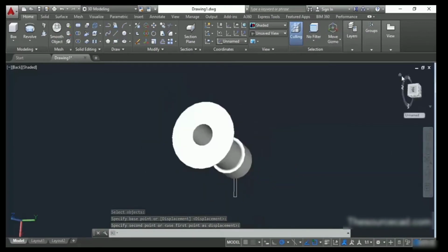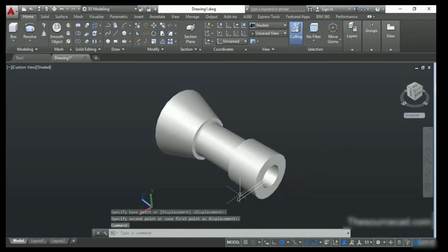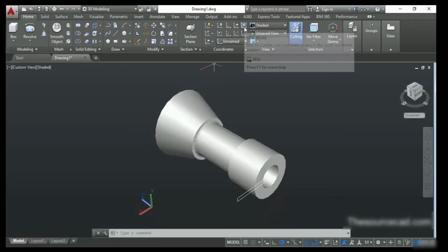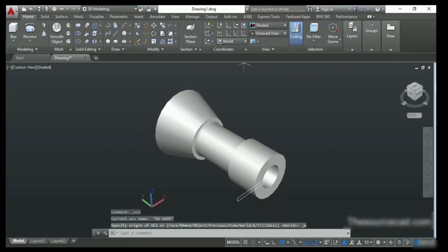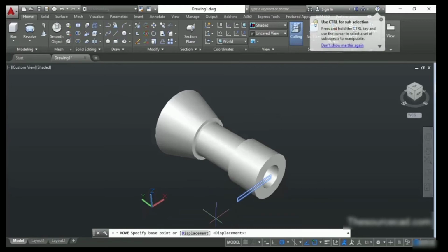Now click on this home icon and let's see where this rectangle is. So this rectangle is not at the correct position which we want. So we need to move this rectangle to the top of it. For moving it, first move on to this world coordinate system and change our coordinate to the default values which it was initially. And now select this rectangle.